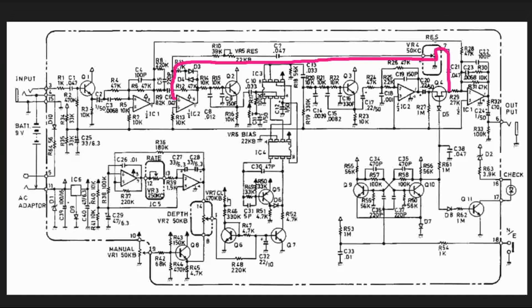And in this path, this VR4, let me go ahead and clear out this line. VR4 is the external potentiometer with a knob that you turn for the resonance control is what they call it. Okay, it's the amount of feedback that comes back through the loop. But this fixed resistance and this variable resistance set kind of what the maximum value is going to be.